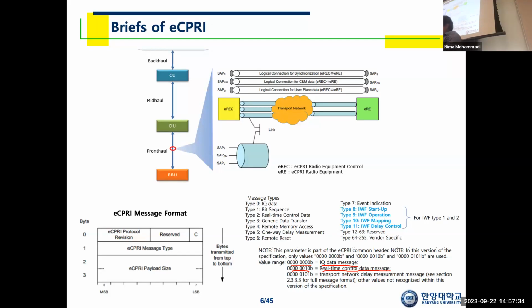C plane message. In order for this U plane message to be transmitted successfully without any error, you want to transmit subcarrier information and subcarrier index and symbol index before you send the U plane message. Before you send that complex valued OFDM sample, you want to specify, oh, this sample, which you will soon receive, corresponds to this subcarrier index and this symbol index.